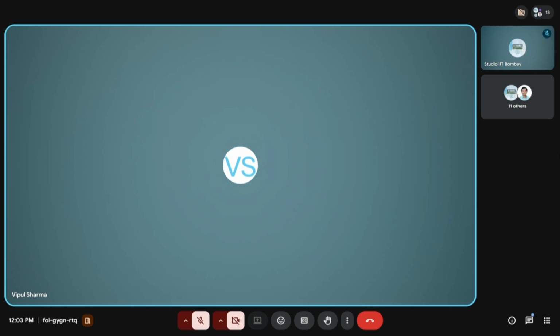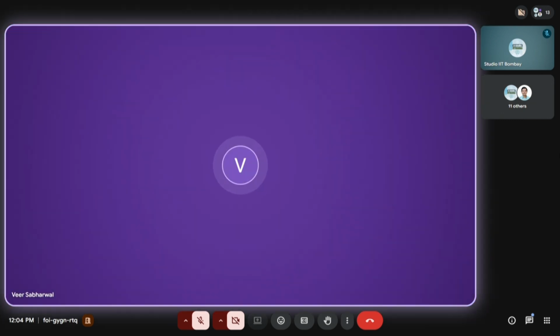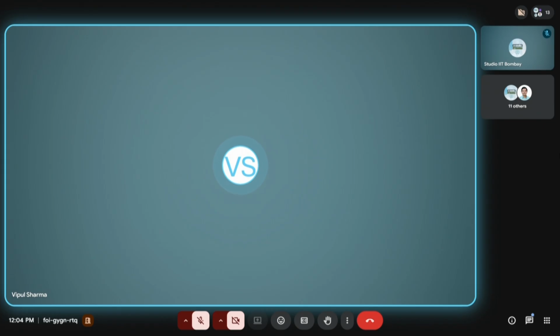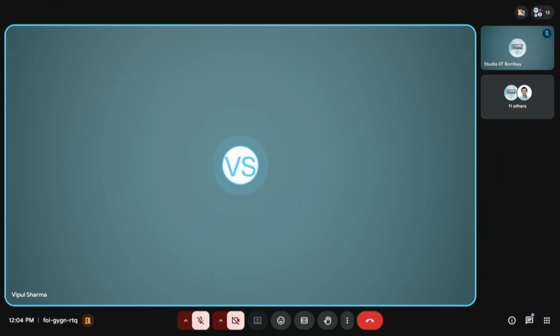That's what I'm telling. Okay, sir, then I will go for a very basic design like CS amplifier only, or some very single stage amplifier, that kind of CS thing. A CS amplifier is a very preliminary circuit. I suggest if you can go for a differential amplifier, let us say, or maybe if you can add a second stage also, because it requires 6 to 7 transistors, or maybe some kind of a ring oscillator, inverter based ring oscillator, or maybe a very basic band gap reference.